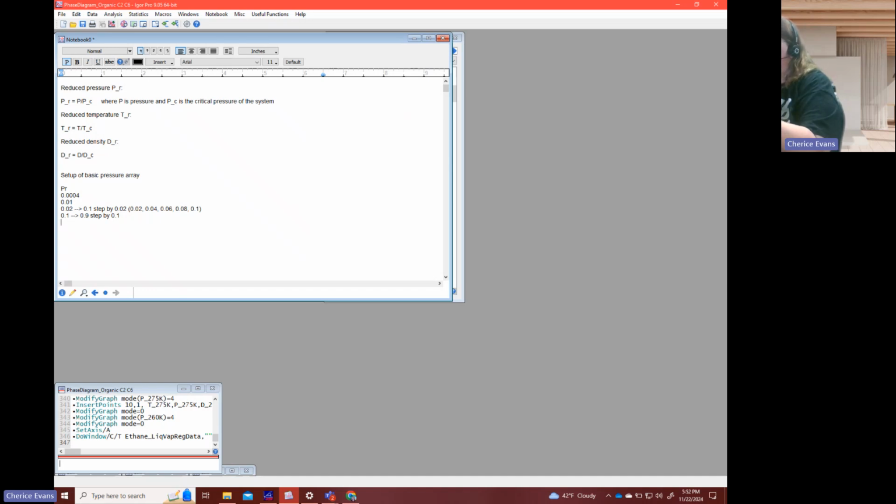And that's that point where I get the most rapid change in density as a function of pressure and temperature. So that is a point where the equation of state becomes the most nonlinear. It's the point where everything exhibits the most dramatic changes. So that's the region where I'm going to, again, need to step a little bit smaller.